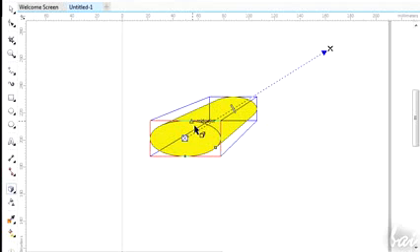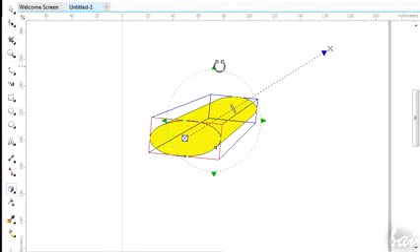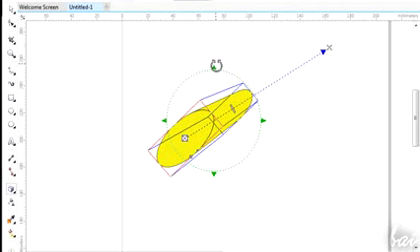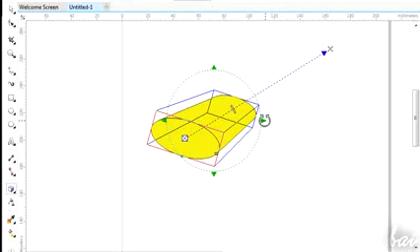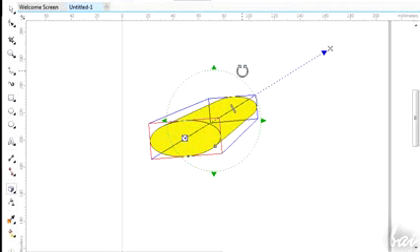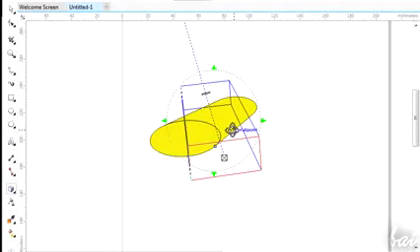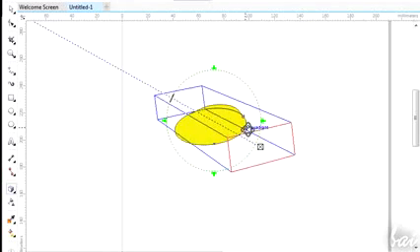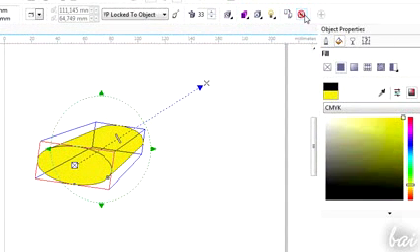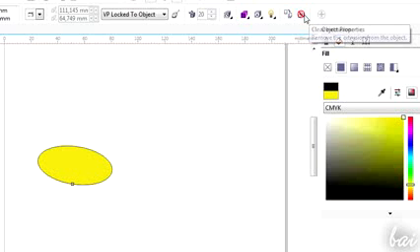If you click once again on the object while the Extrude tool is active, you will be able to apply 3D rotation on the object. Drag on the green arrows to rotate around the direction. Drag on the object to rotate in full 3D. Click once on the object to finish. You can delete this effect by clicking on Clear Extrusion above, when the tool is on.